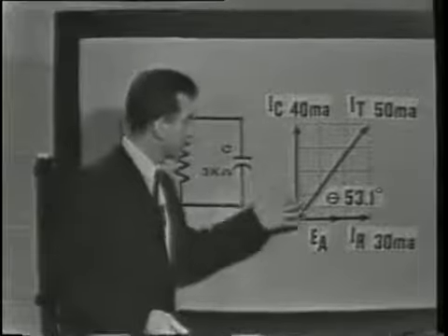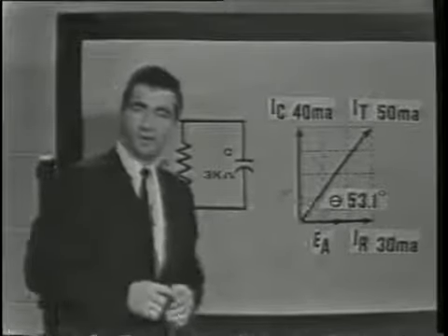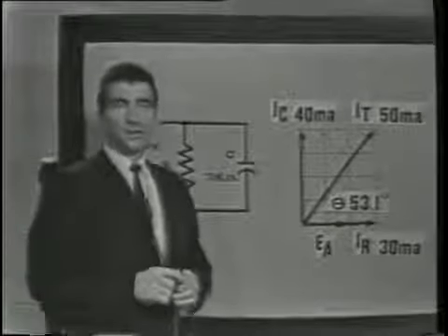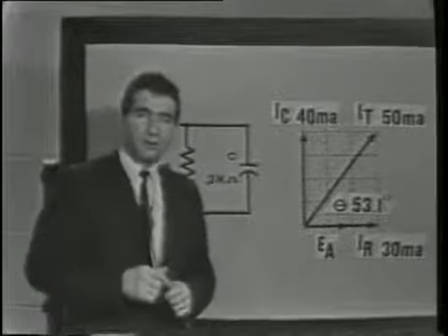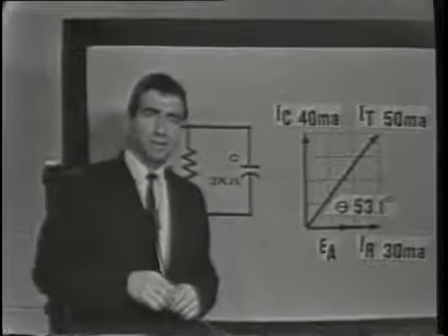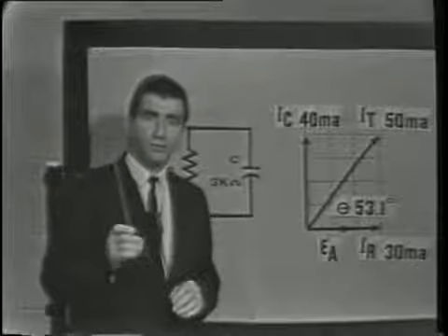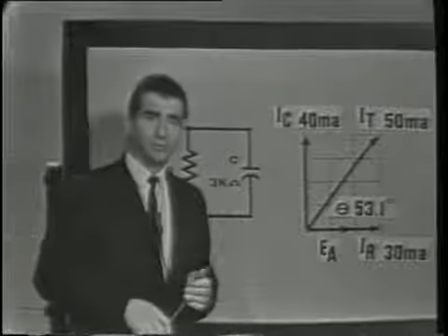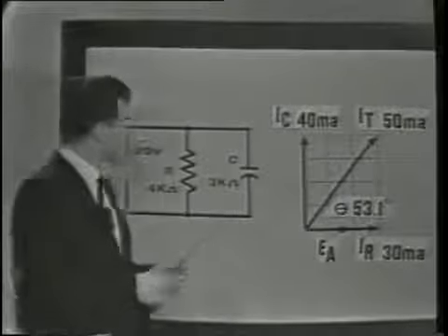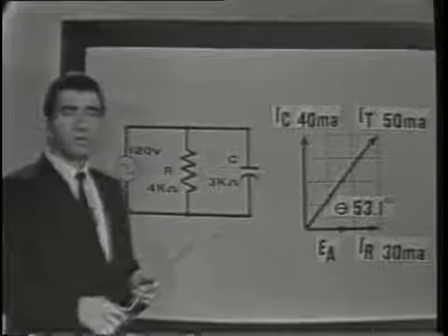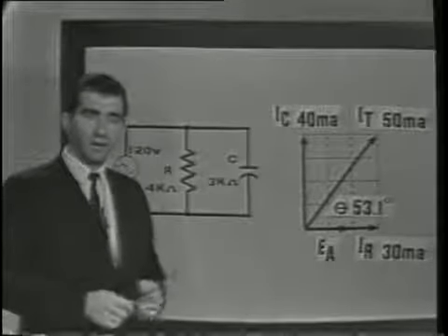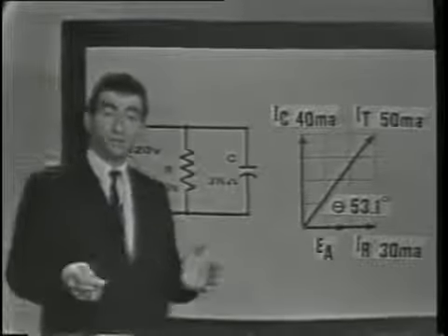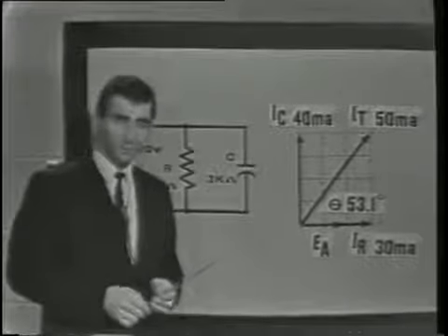Why all this concern over phase difference between current and voltage? Well, it's very difficult to show you the specific reason that phase shifting networks are important, but you can count on finding this principle used in many types of circuits. For example, a network similar to this one is used to start a split phase motor, and in some cases will determine the efficiency at which the motor operates.